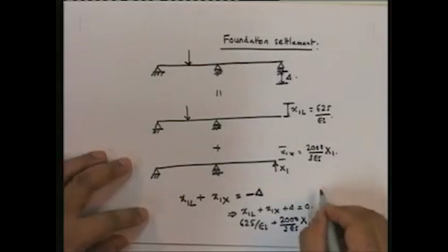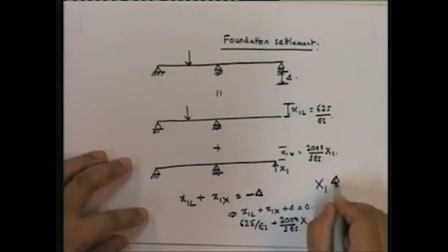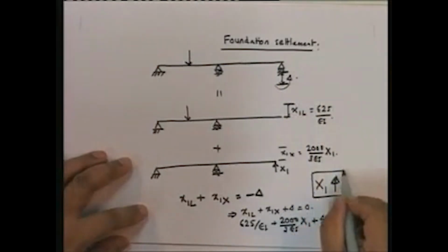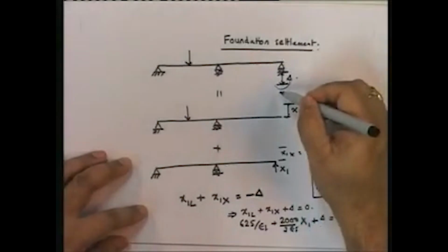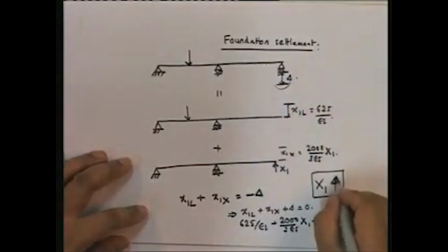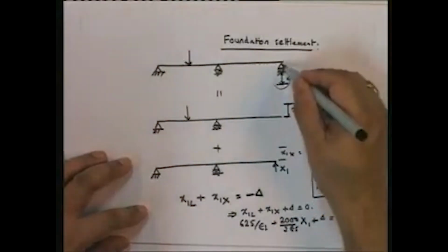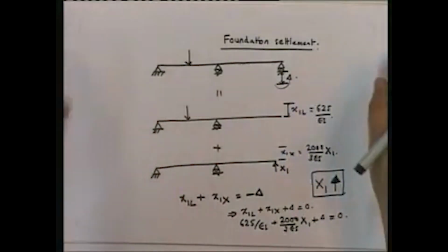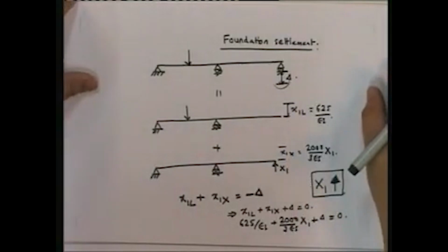And the value of x1 goes up because of the support settlement. That makes sense, because due to the support settlement, this is going to take up a much larger reaction. So foundation flexibility and foundation settlement actually do not affect the solution of statically determinate problems themselves.